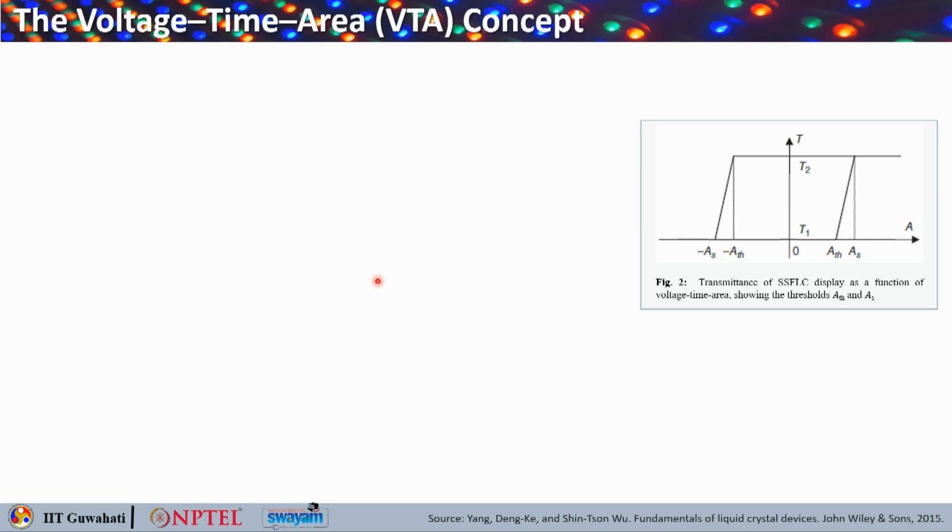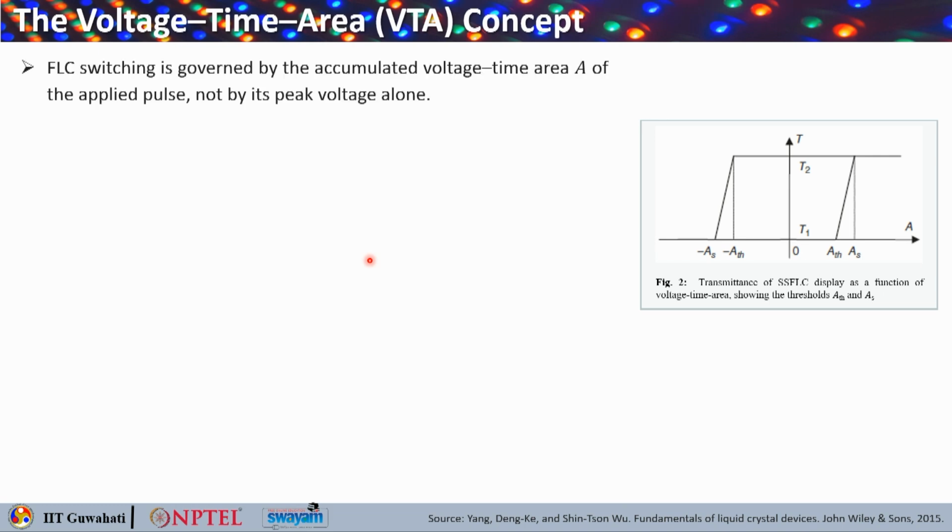Okay. So, here you can see that the voltage-time-area A is important as the time integral of the applied voltage waveform, which is analogous to impulse in mechanics. So, you are basically having the force integrated over time rather than the force itself.